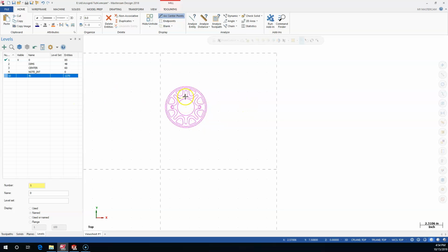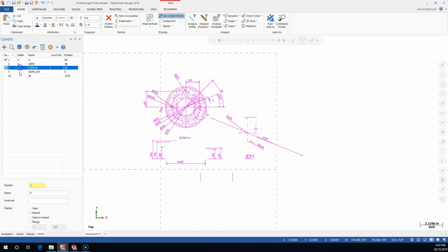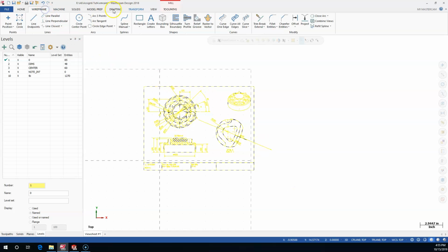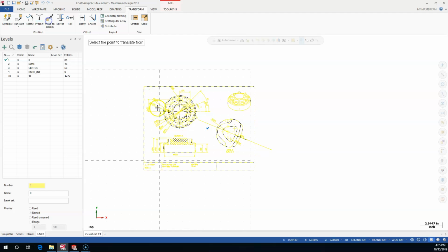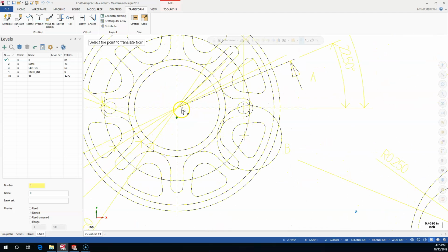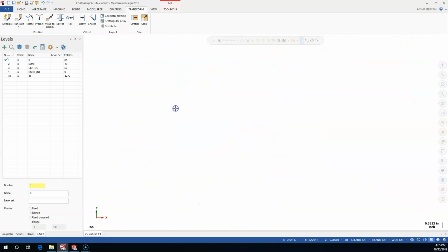So if I manipulate this over into quadrant 4 without the title block, the title block stays in its current position, part moves down. Depends on what you're trying to achieve. But I would say when we move this to the origin, we really want everything to go with it. So we would turn all of this on, grab our selection, we're transforming, move to the origin, make sure I'm getting to that point.